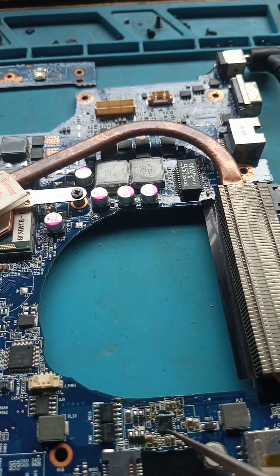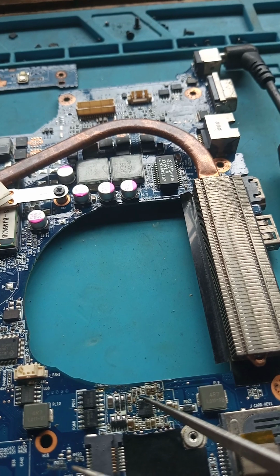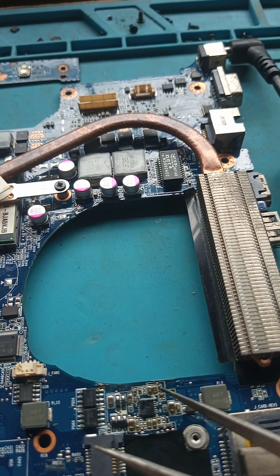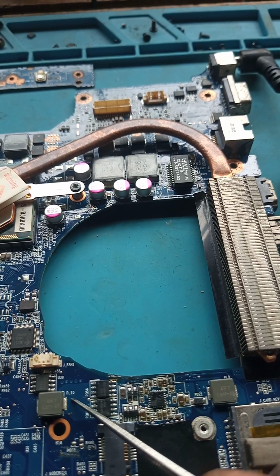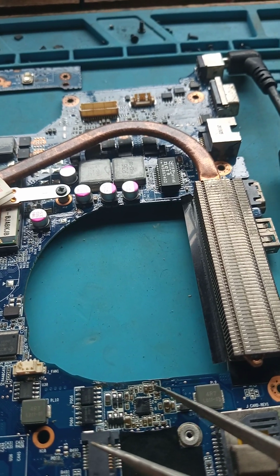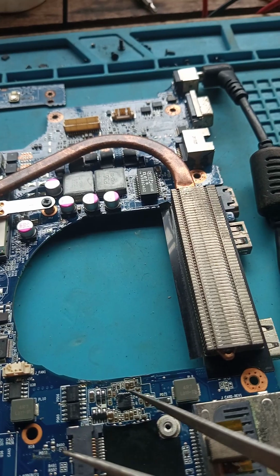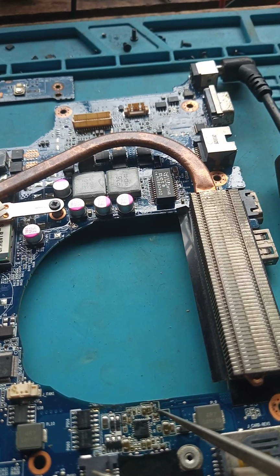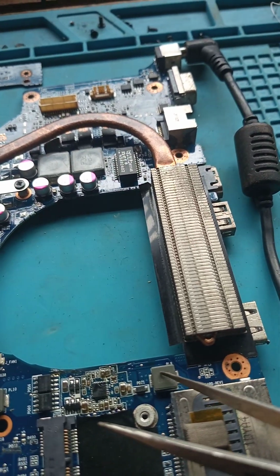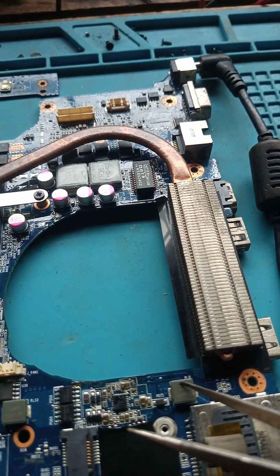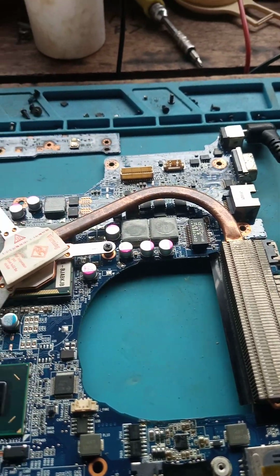So I'm going to inject voltage here, not from this IC but maybe from the LDO3 or from this output. I will inject 3.3 volts here on this resistor. When I inject voltage there, possibly it will generate the enable voltage for this IC to generate voltage for this coil, okay?